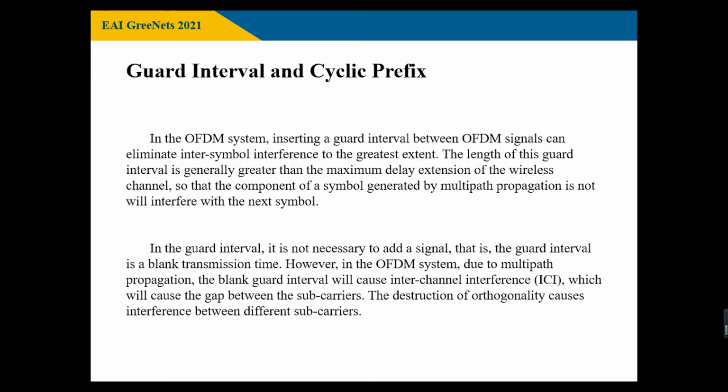Then is the guard interval and cyclic prefix. In the OFDM system, inserting a guard interval between OFDM symbols can eliminate inter-symbol interference to the greatest extent.